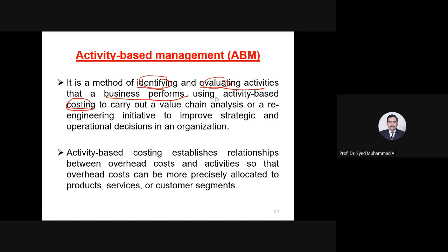Now he can further break down that process: traveling is there, stay is there, how many people are involved, what instruments are used. For example, he's using a total station which has an accuracy of 1 millimeter, but only up to 200 meters. It is a plain area.